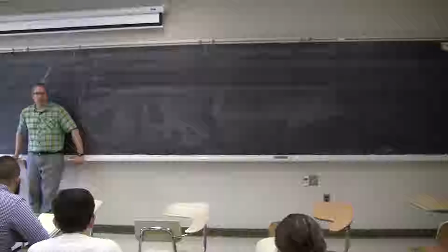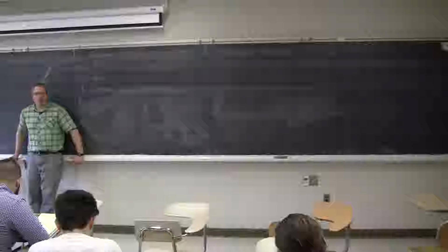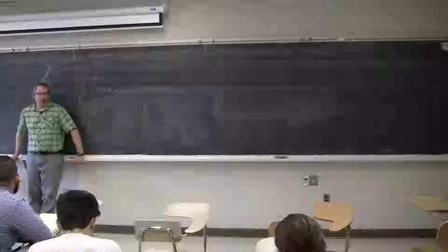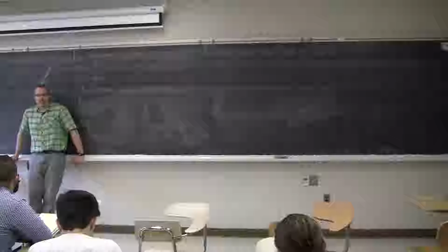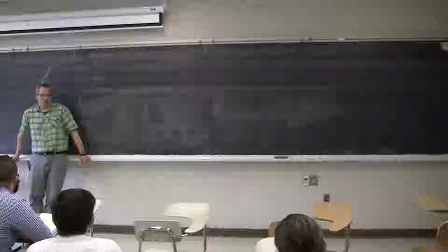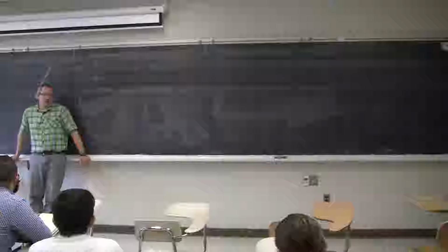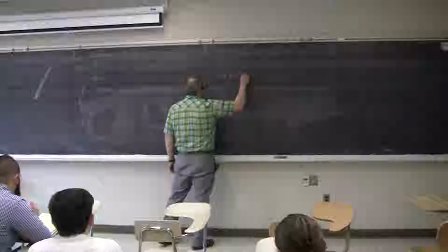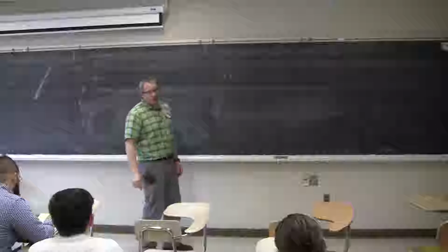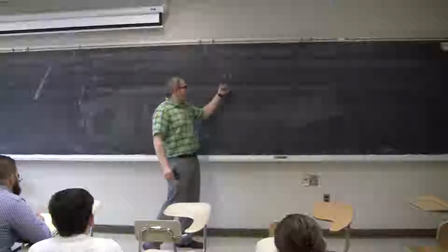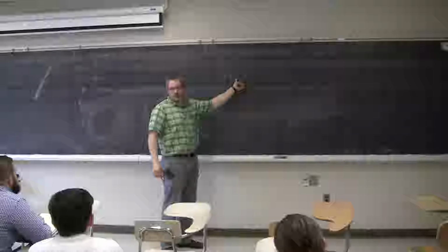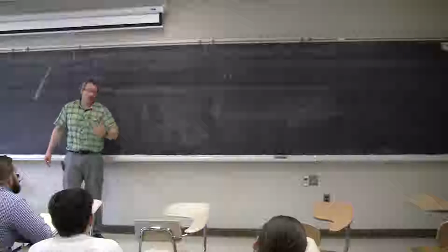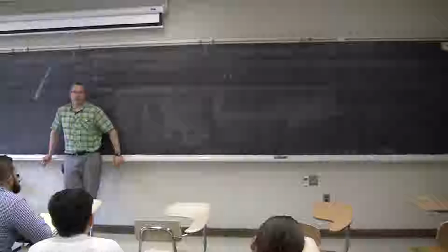If you remember from the lab that we did on Monday where we got the tour, they had one fairly sizable machine that I think was only maybe 100 horsepower, and that was because its operating speed was something like 54 RPM. It was a pretty slow speed. It had a lot of torque, right? Because power, and this is one of those key equations from chapter 1, power equals torque times omega, right? So if you have a low speed and 100 horsepower, your torque has to be way up, right? So the shaft has to be larger, primarily because, or partially because, you're just moving a lot of torque, right?